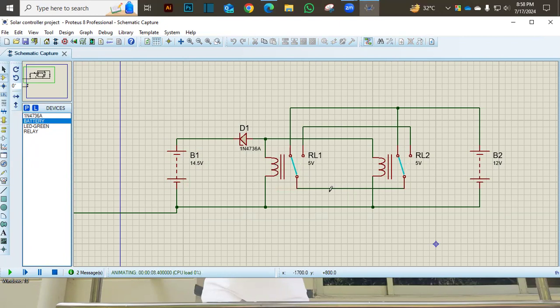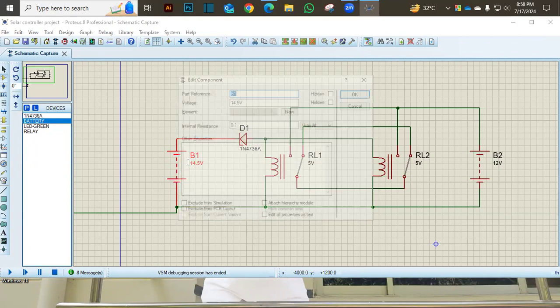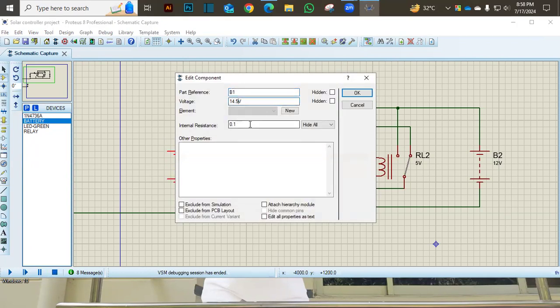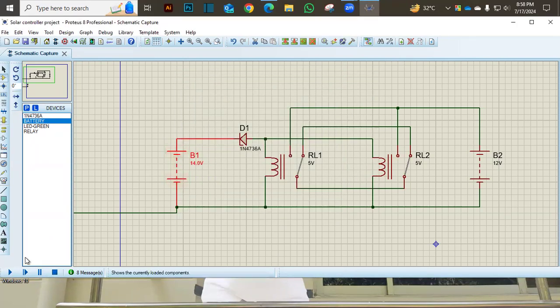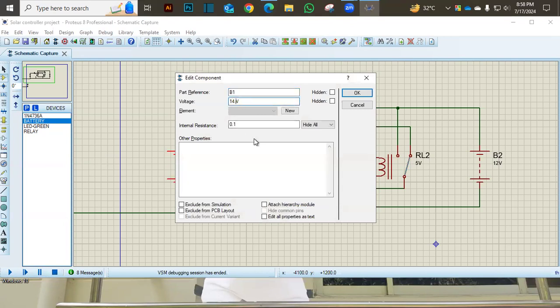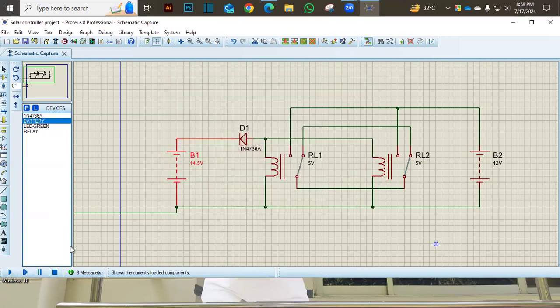Okay. So if our battery voltage is more than 14.5 volt, then our channel will be shifted from normally closed to normally open. What happens if our battery voltage level is just 14.0 volt? Then you can see that our normally closed terminal does not change. So this is our limited voltage, and 14.5 is our cutoff voltage. Okay, you can also sense this system with respect to the Zener diode and our input voltage.